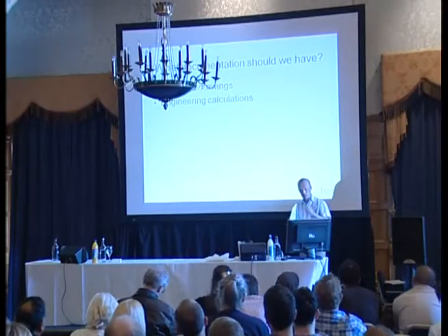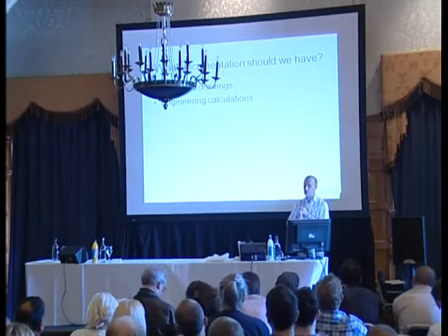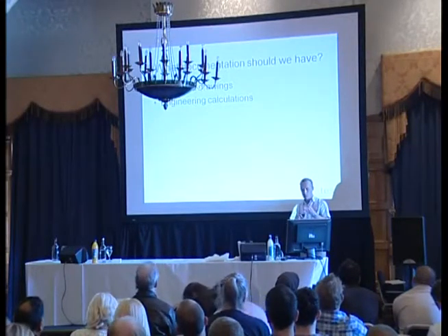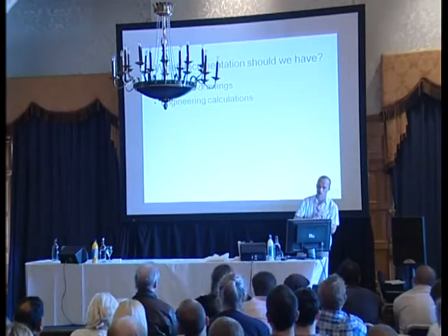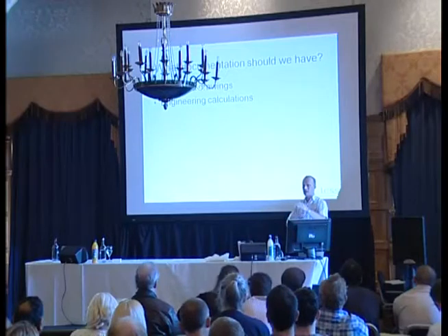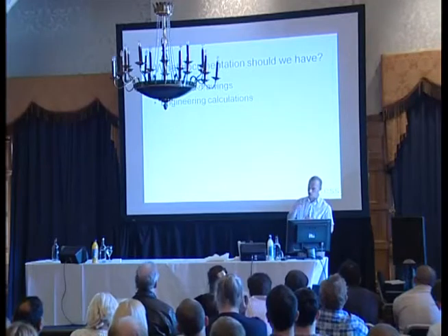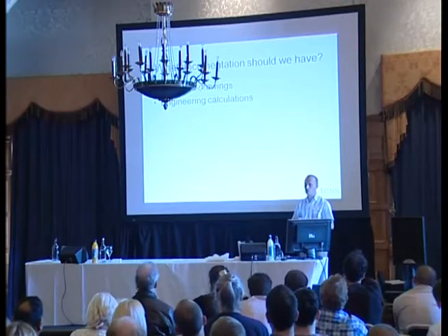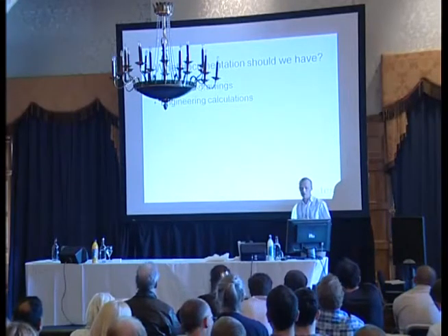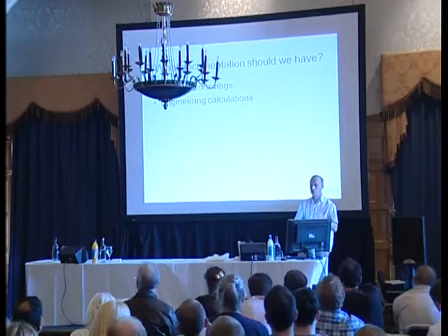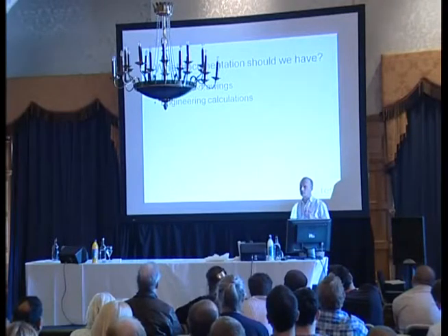Two things really. When's it going to blow down? Blow over, if it's an outside job, okay? So it's failure, wind speed, and what we're supposed to do about tying it to the ground, holding it down, what that's going to require. How you get to the rest of that doesn't actually deeply concern me. But I do need to know whether I need 1 tonne on that corner or 25 tonnes on that corner, that's critical. And even if I do have 25 tonnes, if that stage is going to blow down at 25 metres per second, I need that piece of information.